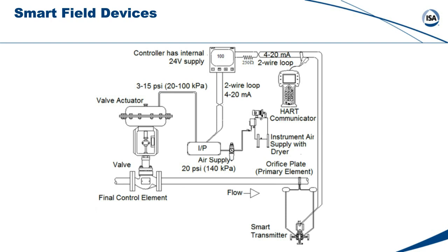We can communicate using this digital protocol, which is called HART, H-A-R-T, from anywhere that we can clamp onto the circuit with a handheld or PC-based configuration terminal, whether it is at the transmitter, in a junction box, or in the control system I/O panel. This allows us to service the transmitter without having to be in a hazardous, hot, wet, or other restricted environment.